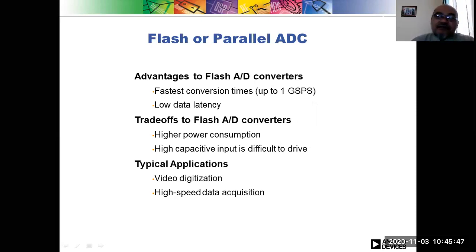Data latency here refers to the delay. With SAR or pipeline, if your analog input changes very fast, then you may lose some of the data because the next conversion is done after several clocks. In the case of flash, it is very fast.